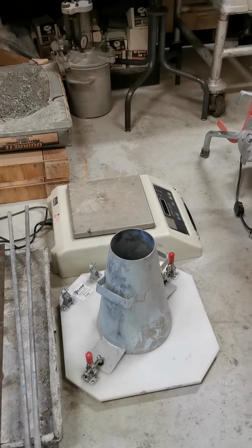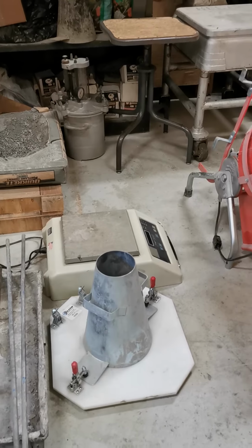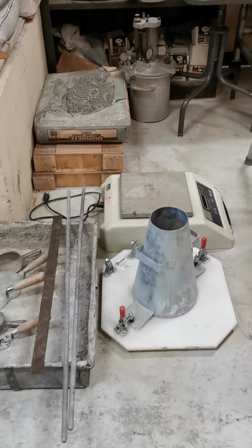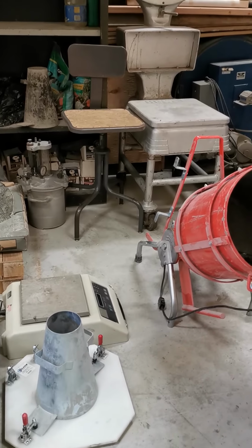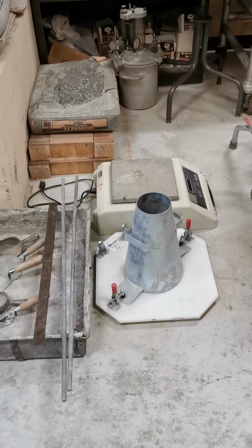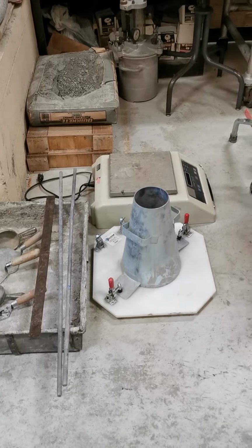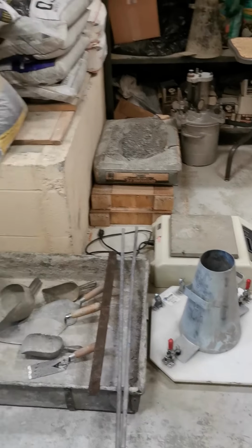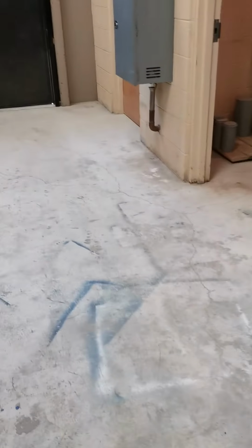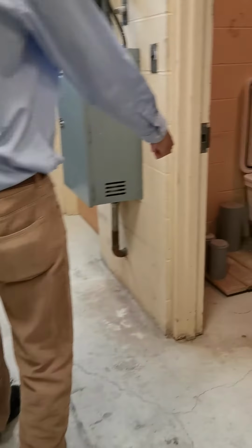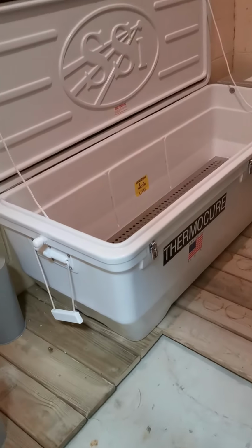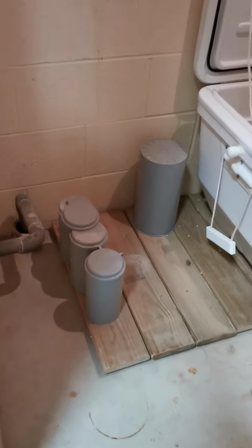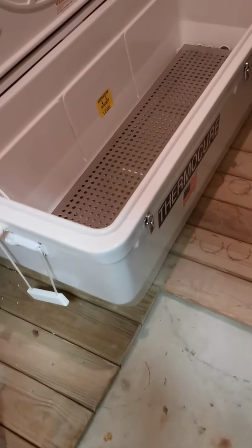The students perform the slump test on the prepared concrete mix to ensure that it matches their assumptions in the mix design calculation. And if the slump is satisfactory, then the concrete is poured into the 4x8 plastic molds and placed into the curing chamber, which has temperature and humidity control.